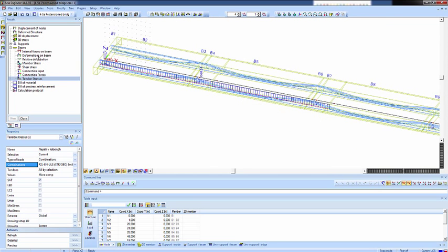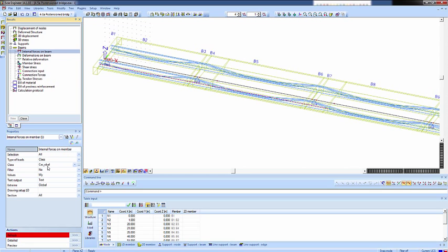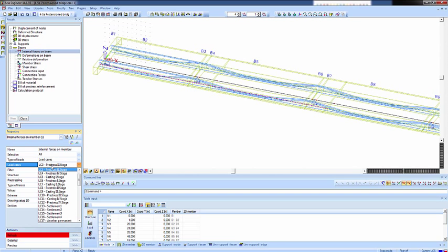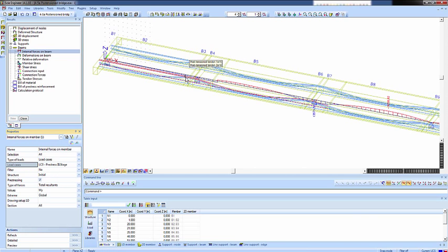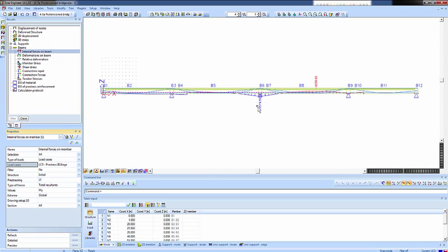Now I can also immediately inspect what, for example, certain results are in a certain phase. For example, let's say I'm going to pick the load case where certain prestress elements are applied. So all the tendons which are connected to LC3, load case 3, all those tendons together, they will apply this moment.